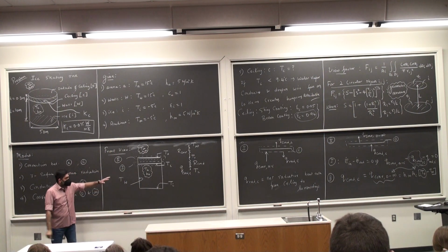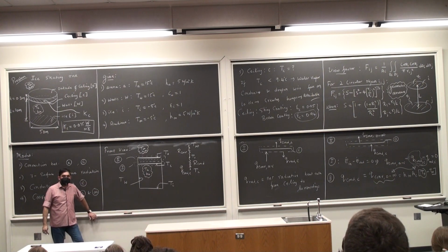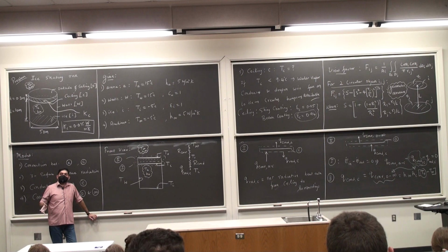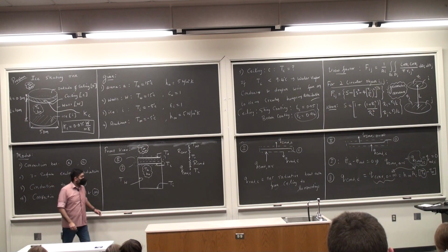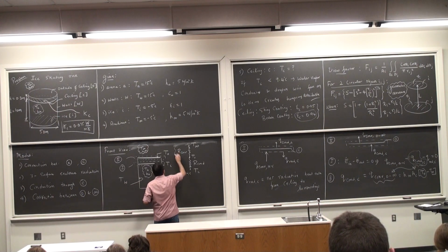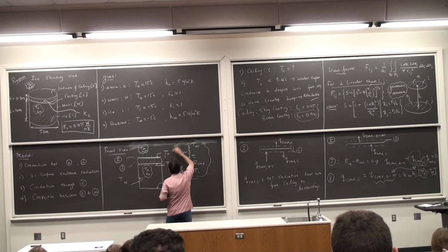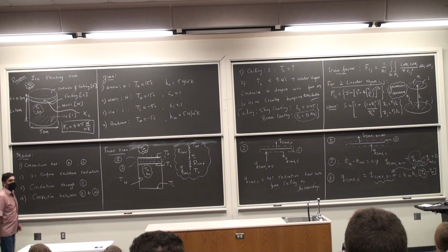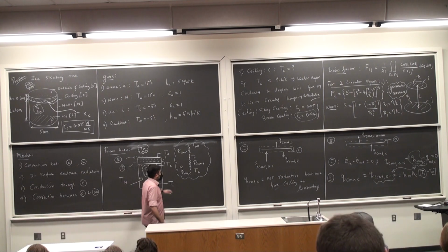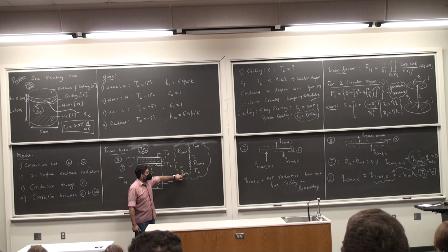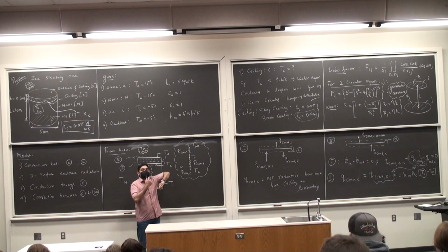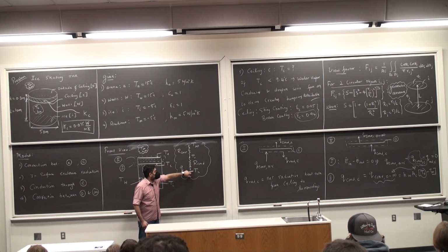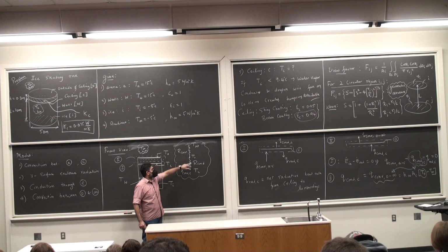I want to make sure this is okay with everybody. This has nothing to do with the radiative resistance network, which we are going to come to next. So this is the key. So rather than use the surface energy balance on control volume 2, which is kind of useless now, I will use Q conduction as the current flowing through these two branches. And so I will write it as Tc minus T infinity divided by the total resistance, R conduction and R convection.